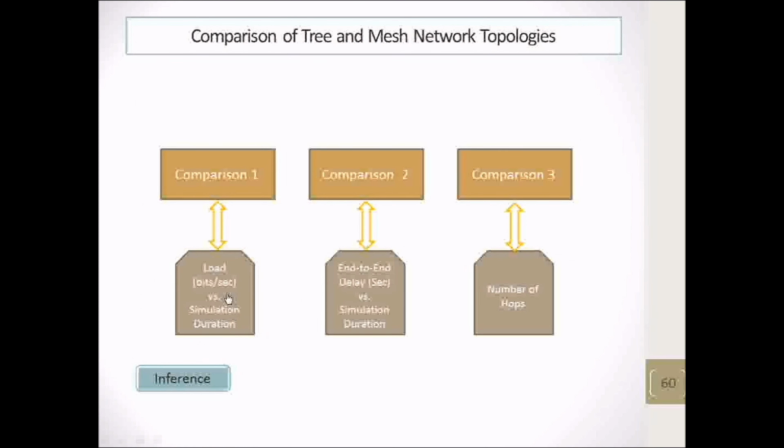Similarly, this Zigbee module is associated with the forest area, and the red and the black wires correspond to the power supply plus 5 volt and ground respectively. Now for serial communication, the yellow wire connects PB2 of port B of the microcontroller to the receiver pin of Zigbee, and similarly the green wire connects PB3 of the microcontroller to the transmission pin of Zigbee. Now this is the hardware output. From the battery we get 12 volt, and from the regulator output we get 5 volt.